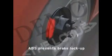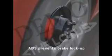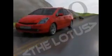With ABS, when the driver fully applies the brakes, the system uses sensors to detect any brake lockup and rapidly pulses that brake to prevent it from locking. This helps to prevent skidding so the tires can maintain grip. It also helps to allow the vehicle to be steered around obstacles while braking.